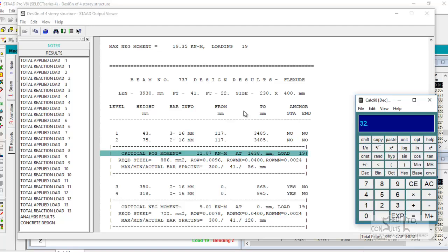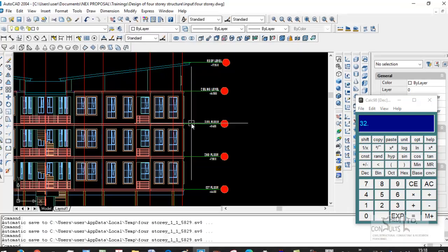32. So what it is telling you is that from this 43, if you add half of this 16 mm, so half of 16 plus half of 16 again, it's the spacer between this bar and this bar, which is a 16 mm bar. So you have a transverse spacer, which is 16 mm. If you add that 16 mm to another 16 mm, you have 32. That gives you this bar. Let me explain it a little better in detail using a drawing.